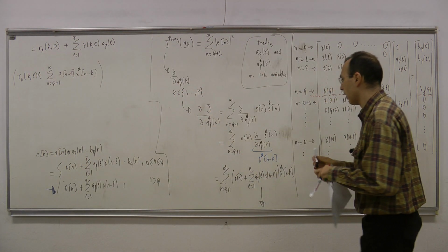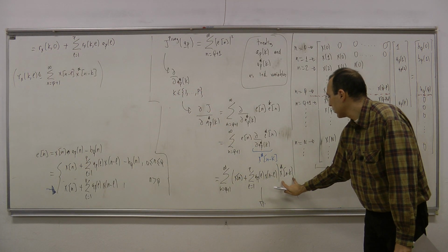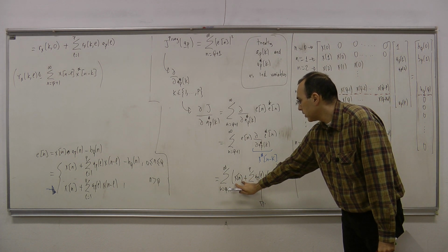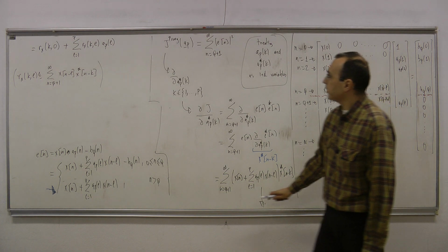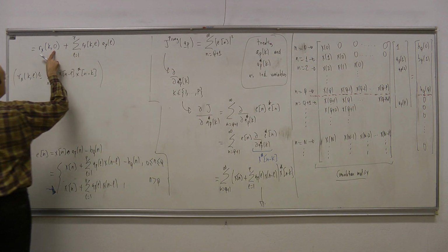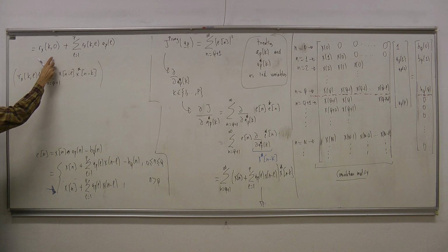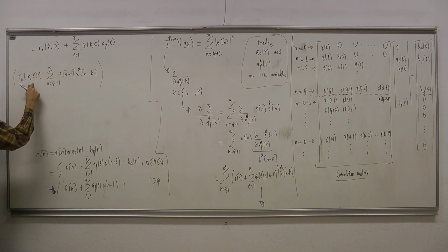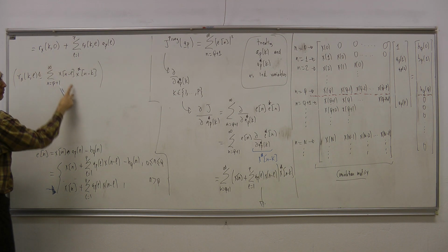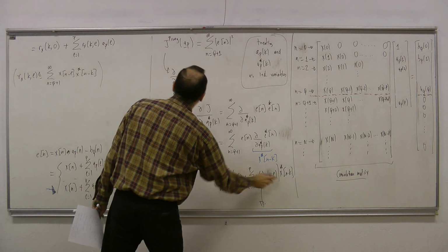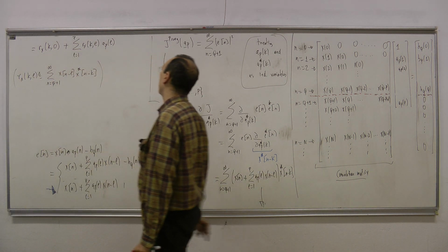So what's going on? Now, x conjugate of n minus k is multiplying this x of n, and I have this summation. So I'm calling that sum at the end r_x(k, 0). Let's see whether it matches. When l is equal to 0 over here, well, I have x of n, this thing, multiplied by x conjugate of n minus k. Indeed, it is the case.